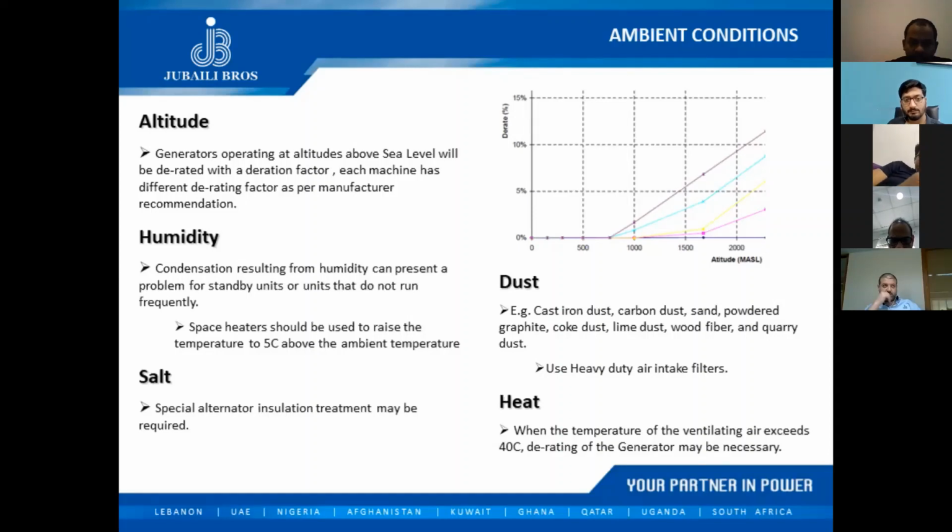Also, with higher temperature, ventilation is less effective. Ventilation or cooling down of my engine is less effective. Okay. It's less efficient. That's why my engine output will degrade with the increase in ambient temperature and with the increase in altitude.